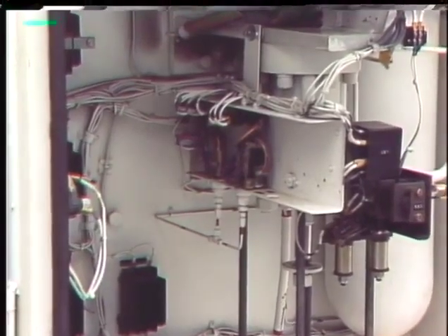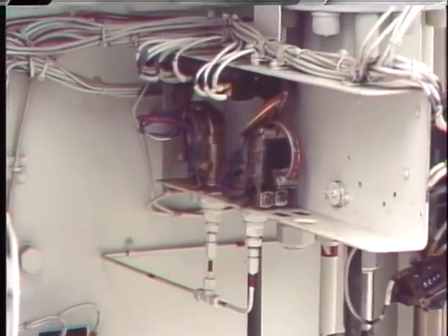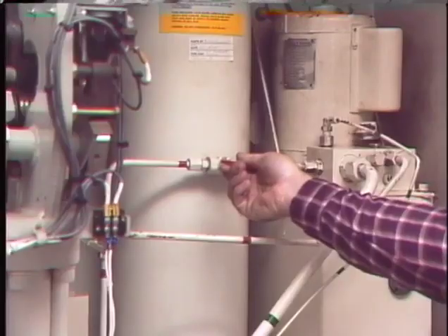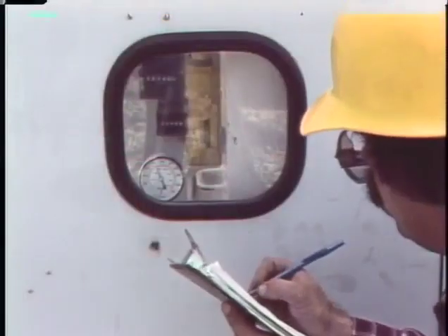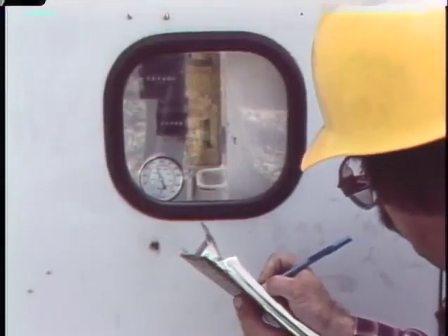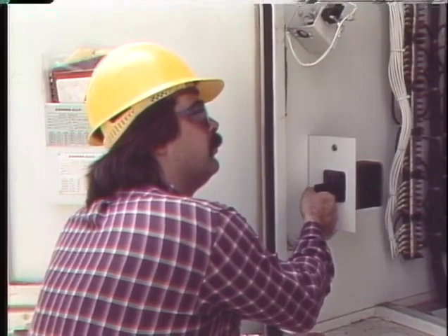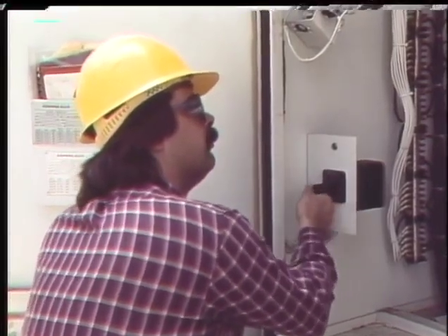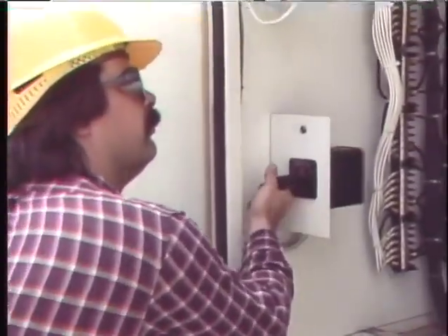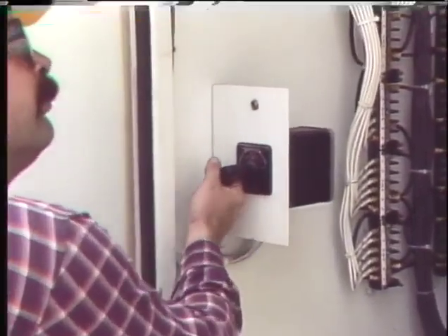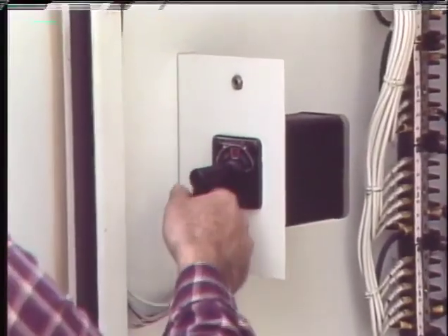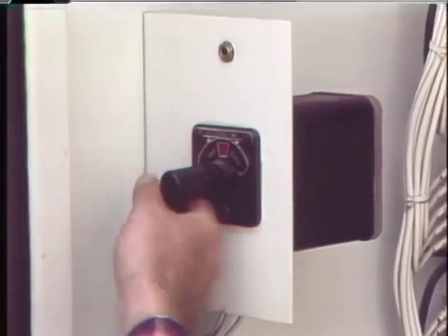A hydraulic operating mechanism will have a governor switch, a low-pressure alarm switch, and a low-pressure cutoff switch that work much like the switches we looked at for the pneumatic mechanism. The switches are checked in much the same way, by bleeding system pressure and noting the pressures at which the switches operate. After checking the pressure switches, repressurizing the system, and making sure any blocking has been removed, you can operate the hydraulic mechanism to determine how many times it will operate on a full charge of hydraulic pressure.